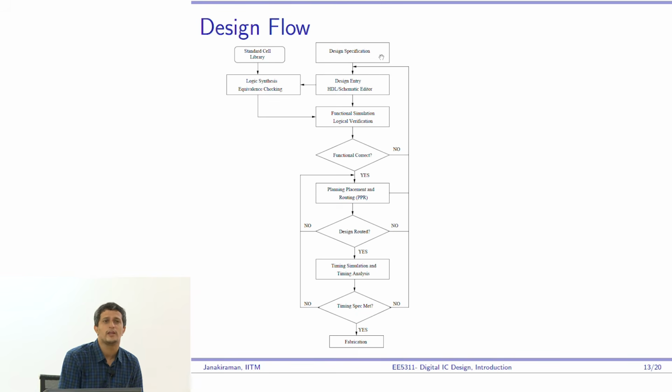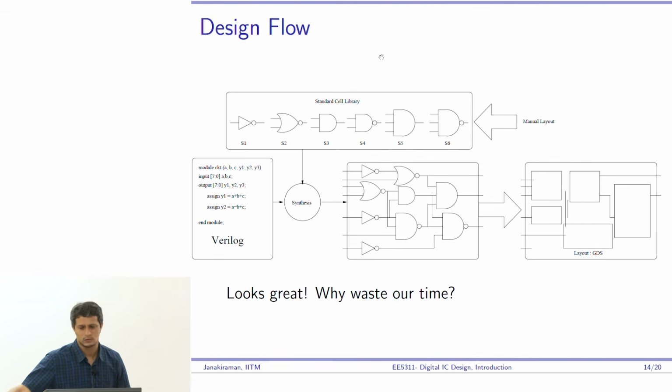Digital IC design is a very fundamental digital circuit design course where we are going to deal only with transistors, okay? And that's what I'm going to teach. So if you look at the design flow, you have something called Verilog code here, right? Then you have something called a standard cell. A standard cell is basically a set of gates which have been designed, hand laid out and given to you, saying that, look, these are my universal gates. Now you have to synthesize your circuit just with this. For example, I could have just a NAND gate here and say synthesize my circuit. It is possible, right?